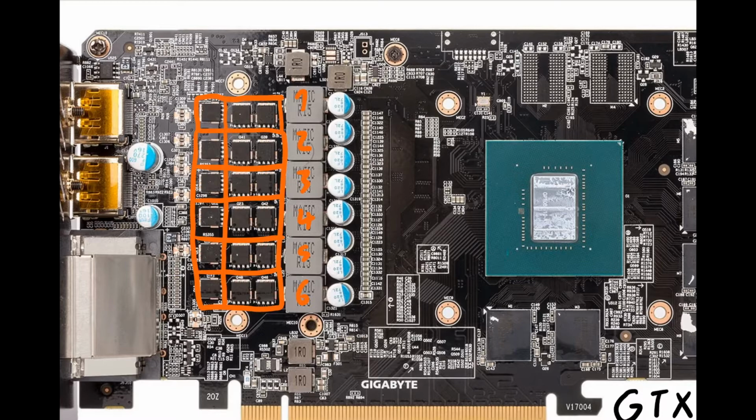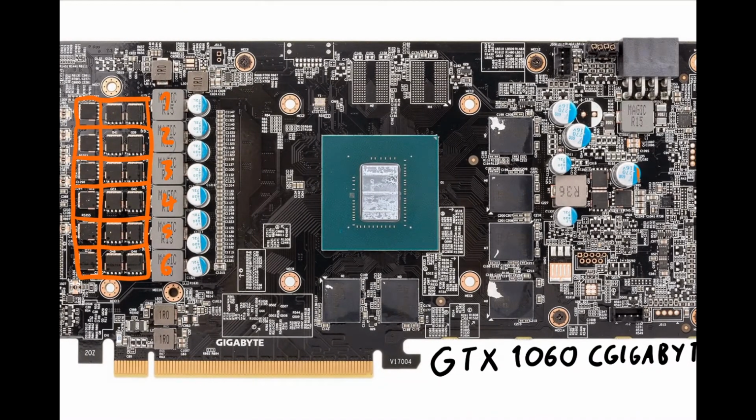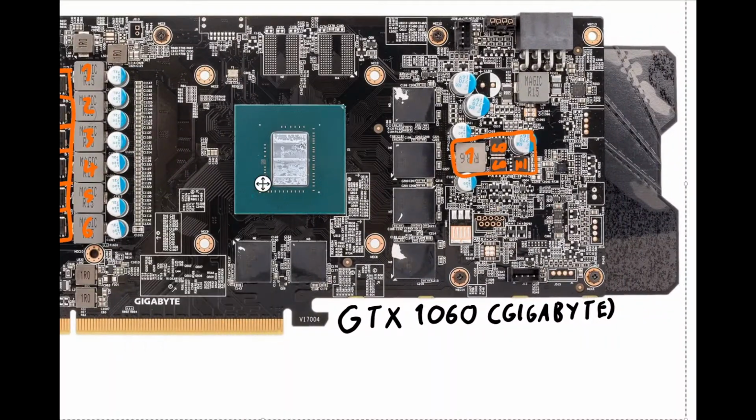If you have discrete MOSFETs, your VRM will basically look like this. So the VCore VRM is very, very likely a 6 phase, and I would have to look up the specific datasheets for the MOSFETs to tell you how good this VRM is. You can apply the same to the VMem VRM. Most of the time that's just less exciting. You have one inductor, and it's just going to be 1 phase, because you only have your high side MOSFET and these 2 low sides. And so you've got your 1 phase of VMem there.